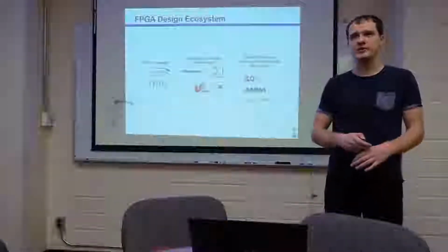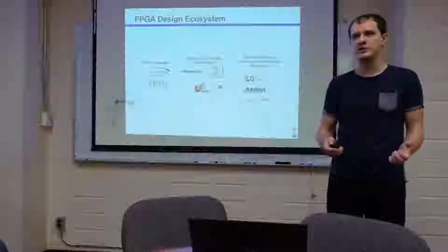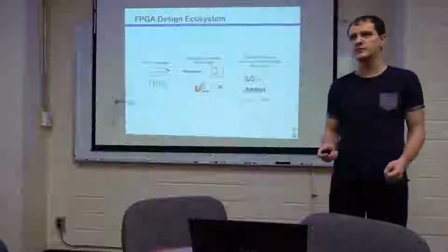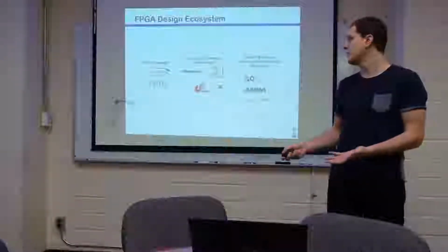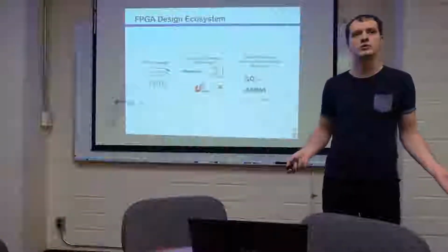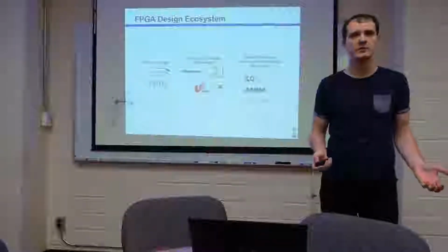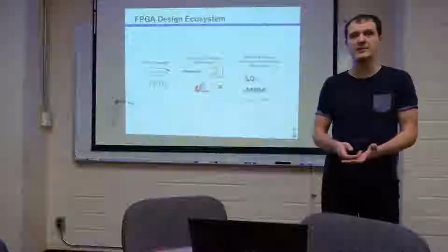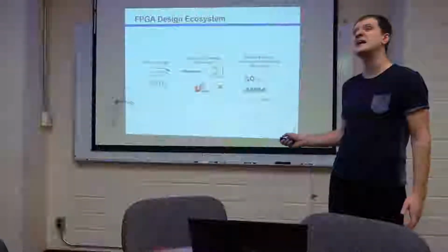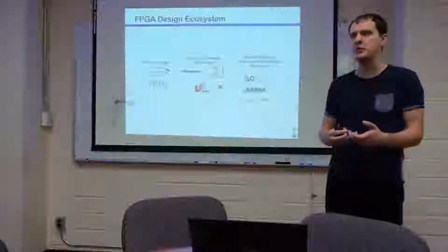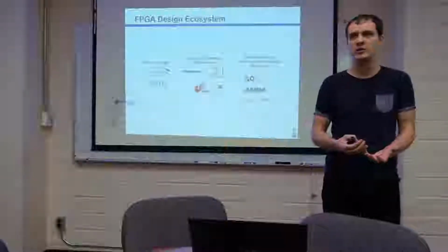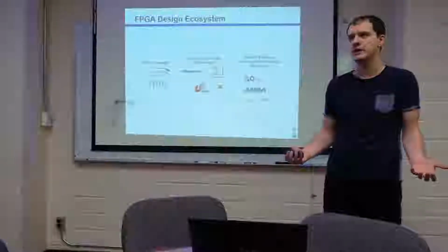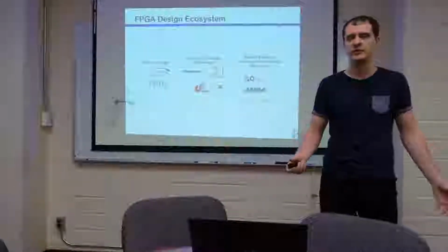So just to give some context of what space we're working in, when we design for FPGAs, we have many tools and technologies available to us. Of course, there's always writing directly in Verilog, which we want to now avoid as much as possible. And different people have taken different approaches to helping us do that. We have HLS tools, which take the more behavioral route, so you can code in a more software-like language, like C or OpenCL, and that will turn that into hardware for you. So this is pretty attractive for people who are used to software because it's behavioral.